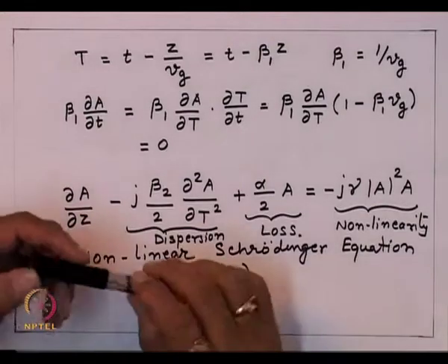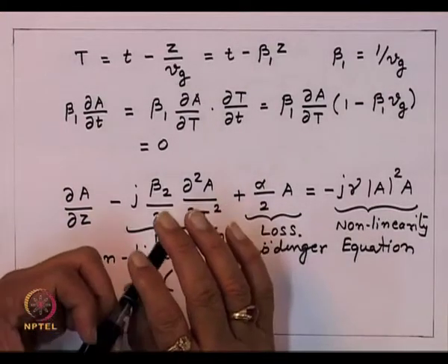We also saw that on an optical fiber, the nonlinear effect is enhanced by almost a factor of a billion compared to the nonlinear effect in a bulk material. That was for the simple reason that once the power is confined to the core of the optical fiber, the nonlinear interaction keeps taking place over the effective length inside the fiber, which, due to very low loss, turns out to be a few kilometers.